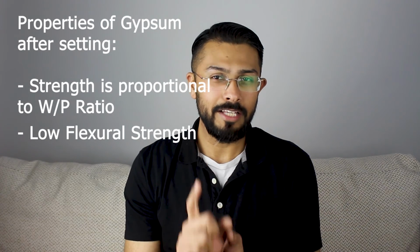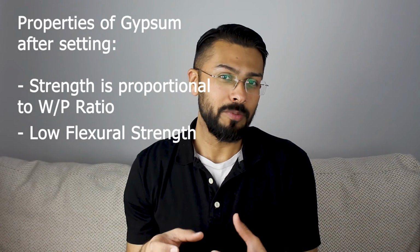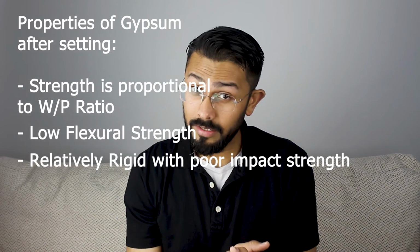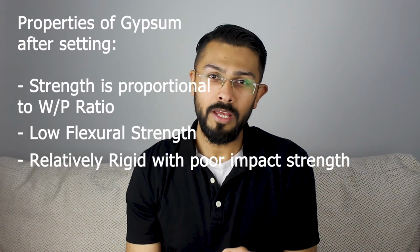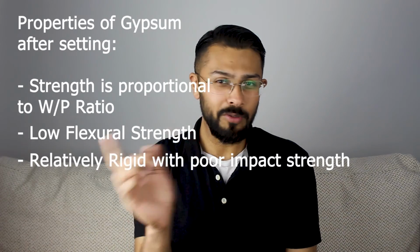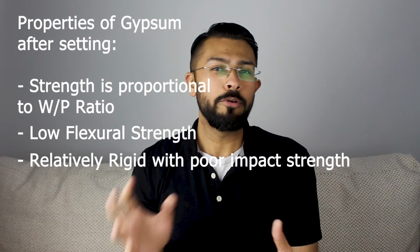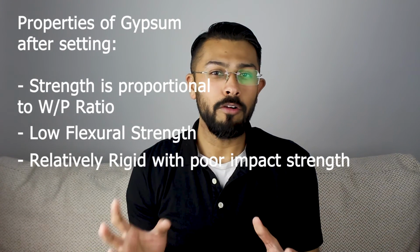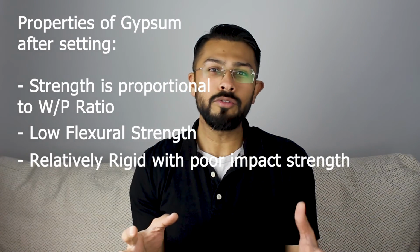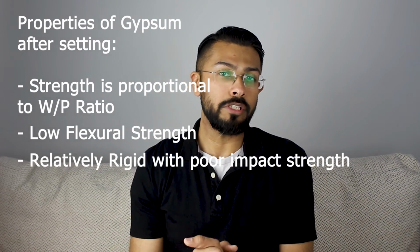Dental stone is less fragile, but it must be treated with care if fracture is to be avoided. It is relatively rigid but has a poor impact strength and is likely to fracture if dropped. We've talked about impact strength in our previous videos, so I'll put a link somewhere on the screen so you can go and check it. Attempts to improve the mechanical properties have involved the impregnation by a polymer such as acrylic resin and the use of wetting agents which enable the materials to be used at a lower water powder ratio.